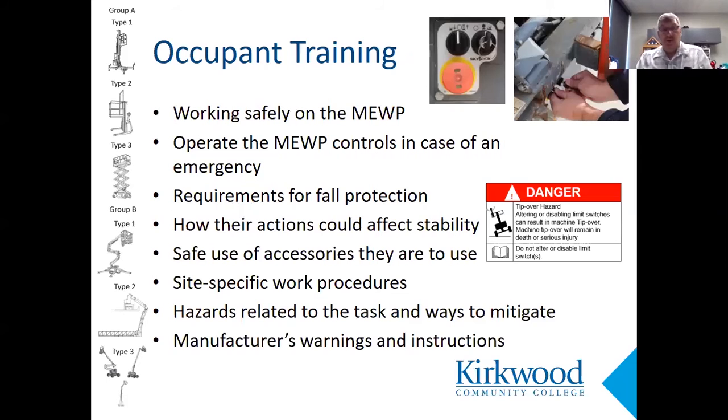Again, you've got your occupant training. This may be a new term to you. You may just take everybody as an operator on that lift, or maybe a sub will come in, and you're not going to take time to train them on the entire lift, so they can be considered as an occupant. Basically, they do need to know some things, though. They need to know how to work on the MEWP safely, some do's and don'ts. Don't climb on the rail. Don't stand on the bucket that's in there. Don't work out, lean over.